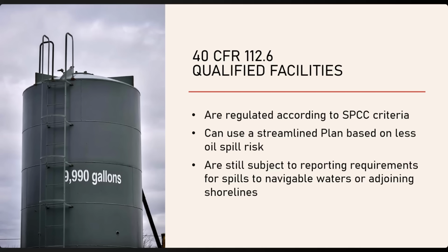First, qualified facilities are facilities that are regulated according to the SPCC criteria discussed previously in Part 1, namely that they have enough oil to meet the 1,320-gallon threshold and also have the potential to cause a harmful discharge to navigable water. The advantage to a qualified facility is that the SPCC plan is more streamlined and can therefore be